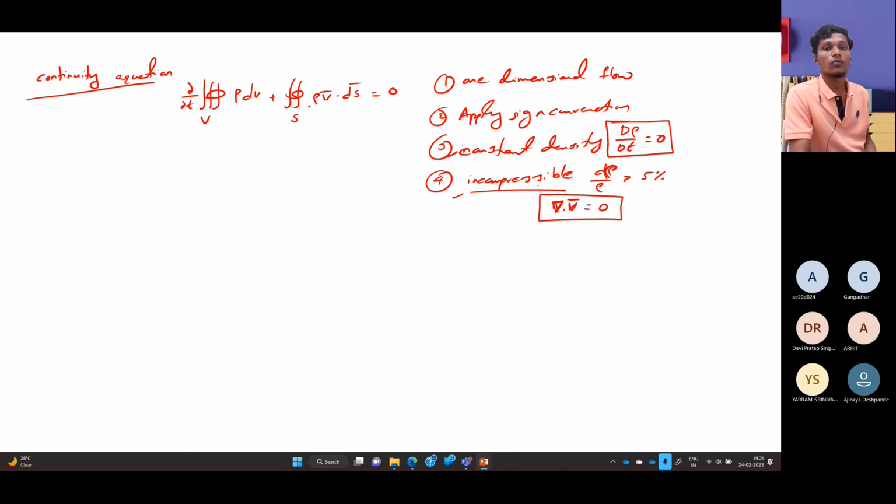So now if you apply all these conditions to the continuity equation for one-dimensional flow, remember that you have only one-dimensional flow, that is, u only, where only x varies, and x and u are the only parameters that you play with, then you will get the very famous relation from our basic physics, A1 V1 equals A2 V2. This is what we generally call the continuity equation in algebraic form, and since density is constant, you can cancel it out on both sides.